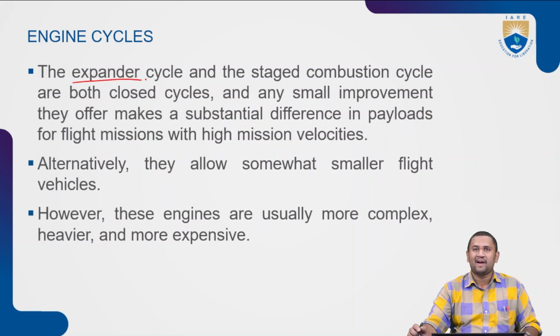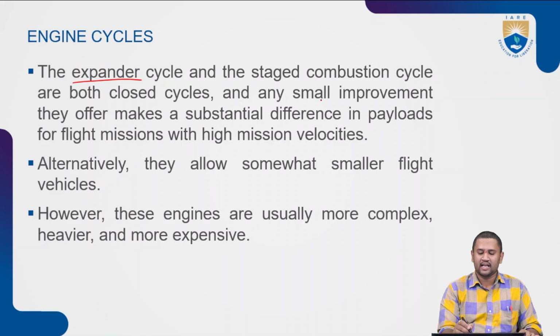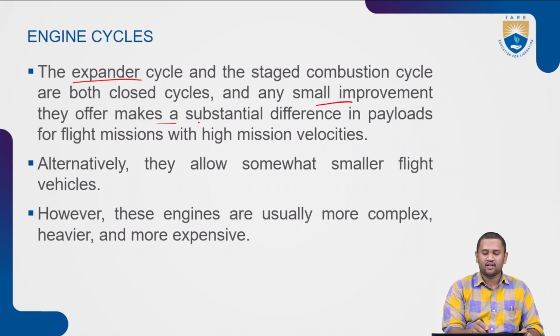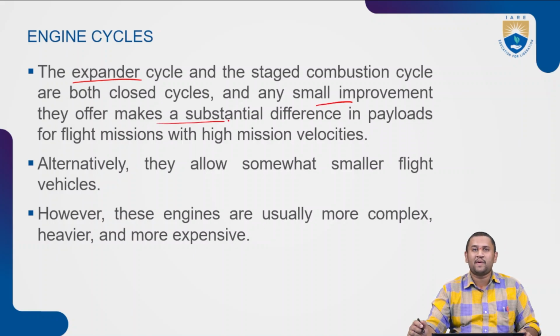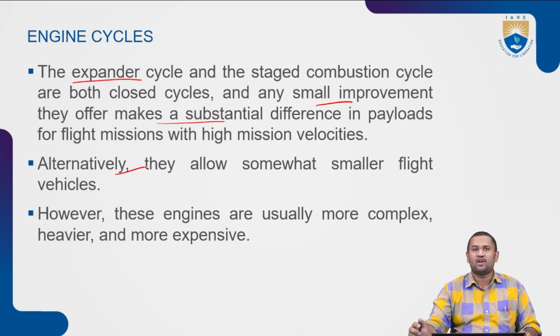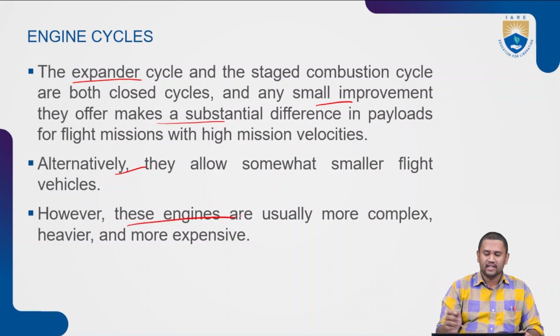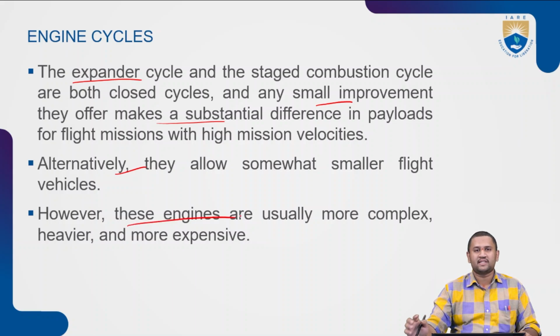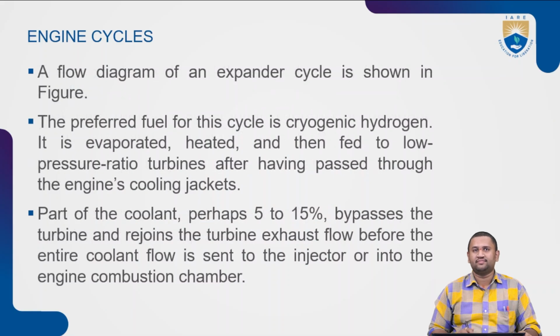Whereas the expander cycle and the staged combustion cycle are closed cycles, and any small improvement they offer makes a substantial difference in payloads for flight missions as well as high mission velocities. Alternatively, they allow somewhat smaller flight vehicles. However, these engines are usually more complex, heavier, and somewhat expensive.